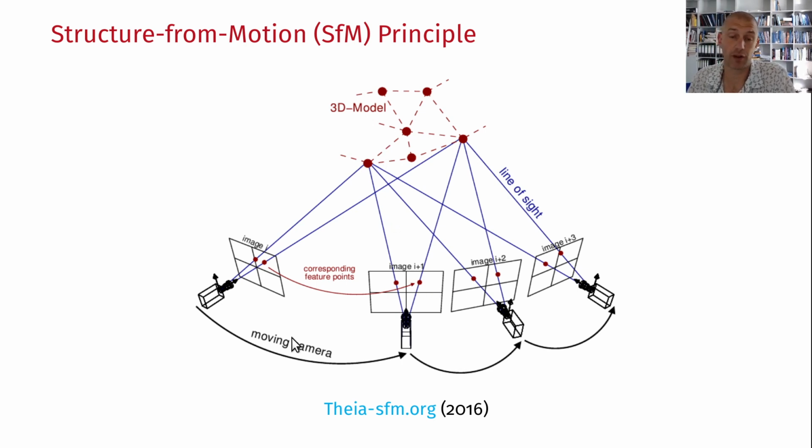They are also often recorded in a convergent geometry. So you see the same point on multiple images, and if you have not only a single point but thousands of points, you can identify the camera position, because there is only one location where the bundles merge, where the camera can be located if you have the 3D information.